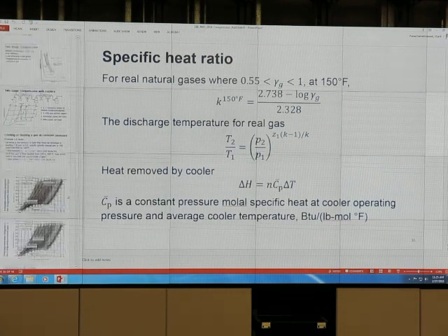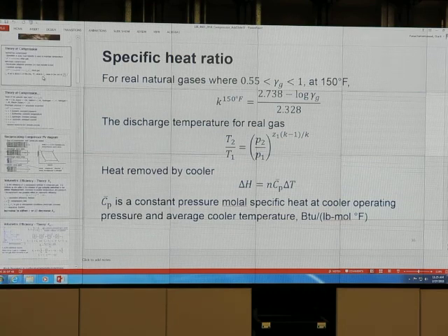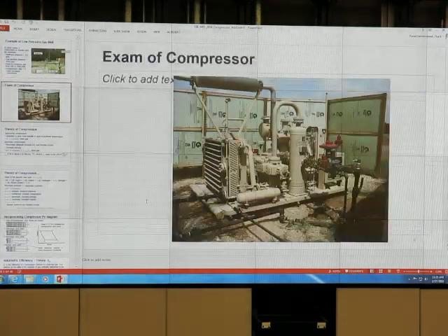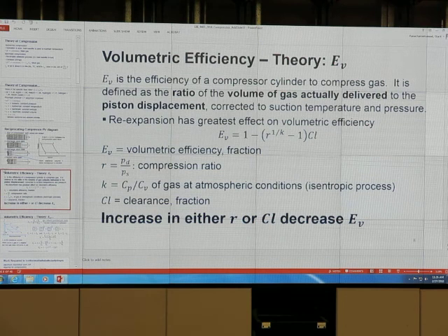I know that you have senior design and everything occupied by senior design, right? Compression ratio. If we go to the previous slide, where's that? Compression ratio, P discharge over P suction. It should stay between 3 and 4, and use absolute pressure to do it.